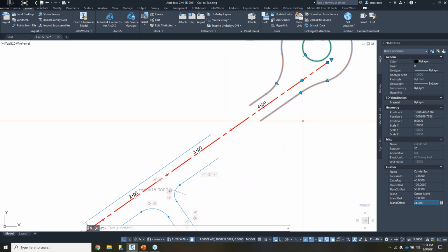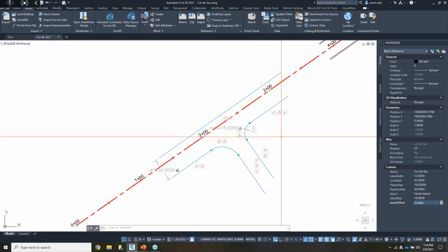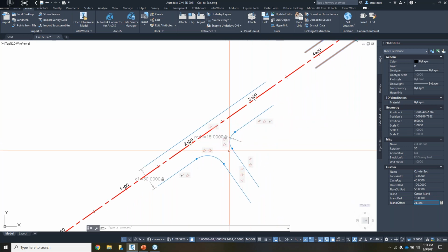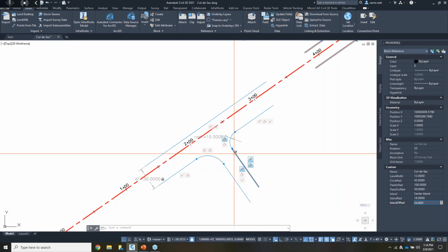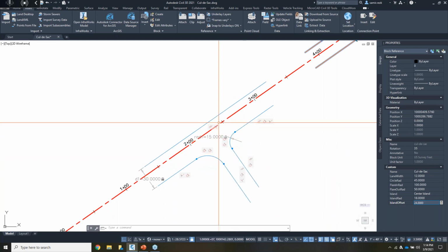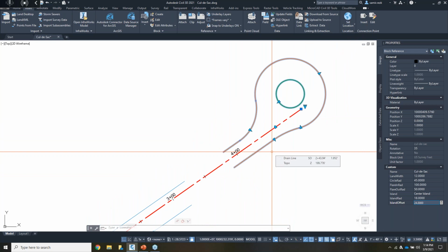So even though the parametric tools in the drawing here are really powerful, the problem is it may become a little bit clumsy. There are a lot of little tags around, and the geometry is all relative to each other, but it's not really contained. It's contained in the drawing. Block parameters are really nice because everything is contained in the block itself, and then we can use that block to just place it in the drawing as a contained object.